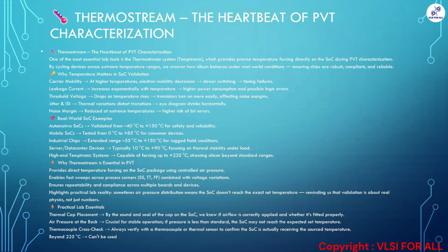So in automotive SOCs, there will be some different ranges of these temperatures. In automotive SOC, we are validating across -40 to 150, like -40, -20, -10, and 10 degrees, 20, 50 degrees, 80 degrees, 100, 130, and 150. Like that, we will vary the temperatures to see the silicon or transistor behavior.